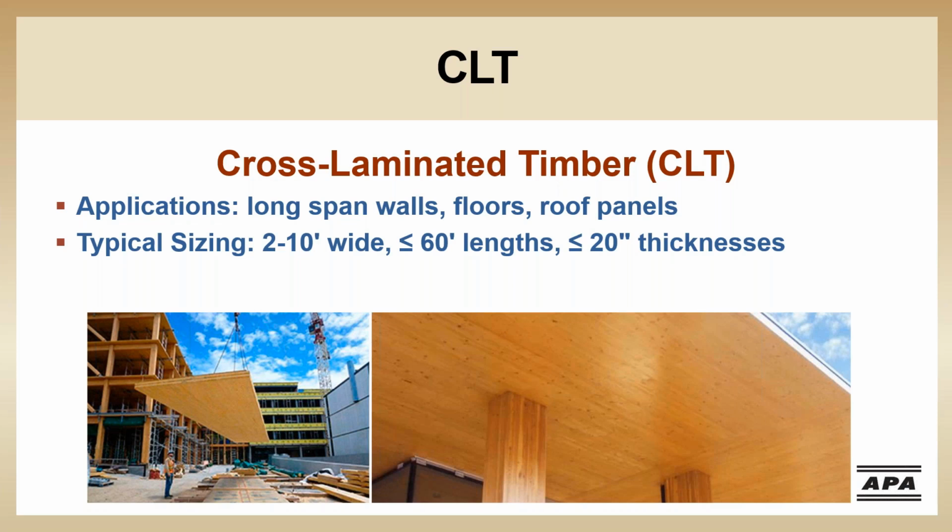And while this pre-cutting of openings saves a lot of time with installation, it does mean that penetration coordination early on in a project is extra important. The panels can be manufactured at custom dimensions, and you should check with each manufacturer in order to optimize your bay sizes. Dimensional limitations are going to vary by manufacturing facilities and their transportation methods. And I would mention that CLT is not a commodity product, so that typically requires early coordination with a specific CLT manufacturer.